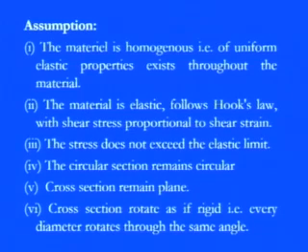So we need to apply our load up to the elastic region only, so that the circular cross section remains circular. Once you cross the elastic limit, there is definitely distortion, and due to this the circular cross section of the shaft becomes elliptical or of some irregular shape. The theory we are assuming has a uniform cross section with uniform stress distribution, which would then not be valid at all.